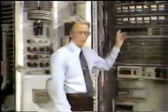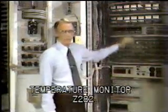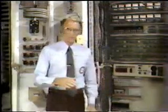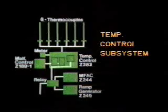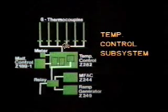The engine temperature monitor, Z282, located here next to the speed monitor, is part of the engine temperature control subsystem. The engine temperature control subsystem activates various components to increase, decrease, or maintain engine temperature. The input signal for this subsystem comes from the thermocouples located here on the aft end of the package. The 6 thermocouples send a signal to the temperature monitor.